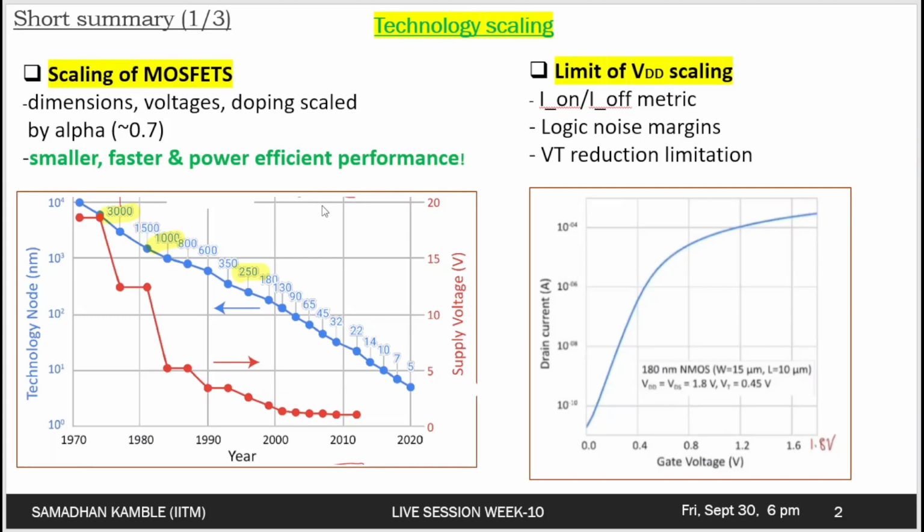If you change the voltages in every node, then all the peripheral circuits that are used, which are the digital chips, also have to be changed, which is not a trivial thing and is not cost effective. That is one of the primary reasons why in the 80s and early 90s the voltages were not scaled along with the sizes, and were kept constant for a couple of nodes and then scaled further. So, as I said, the peripheral circuits bring some limitations to voltage scaling.